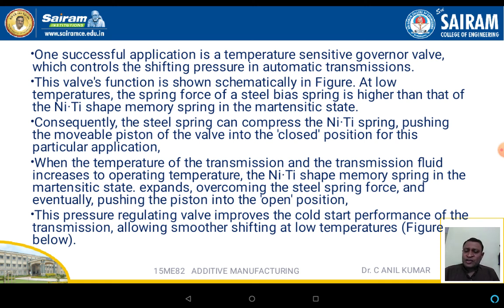When the temperature of the transmission and the transmission fluid increases to the operating temperature, the nitinol shape memory spring in its martensitic state expands, overcoming the steel spring force and eventually pushing the piston into the open position.